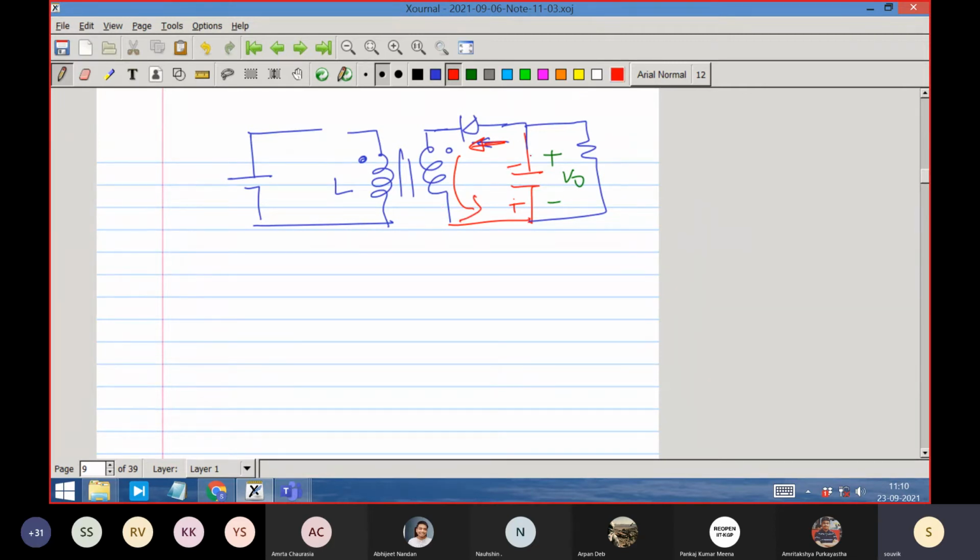And then when it is conducting, you see this V0 is getting applied. The coil voltage is not initially decided by the primary thing. Primary is floating. In the beginning, you can think like that because the switch Q is off. But what is happening? The diode is forcing the voltage, and that voltage is V0 here. So this voltage, convention wise, I will say it is plus minus. Convention voltage is plus minus, right?